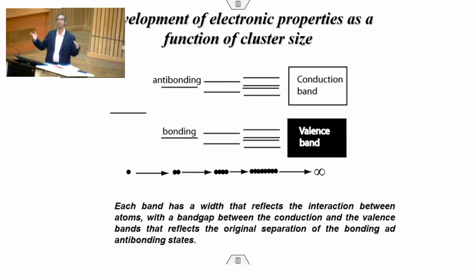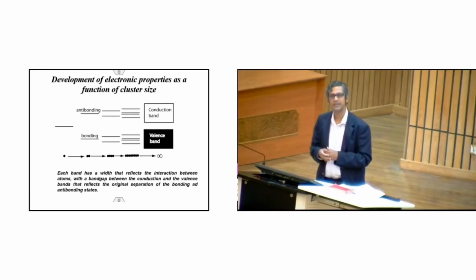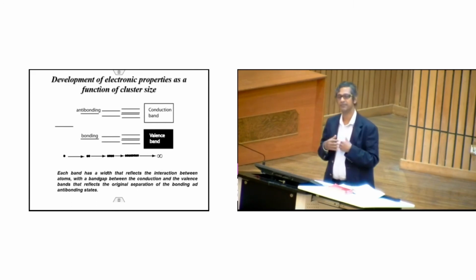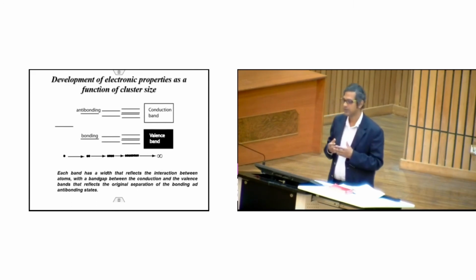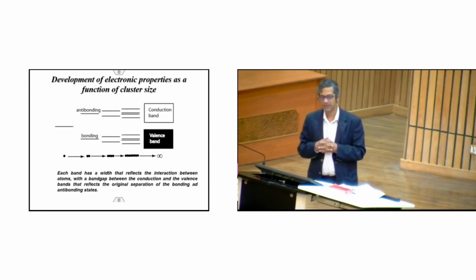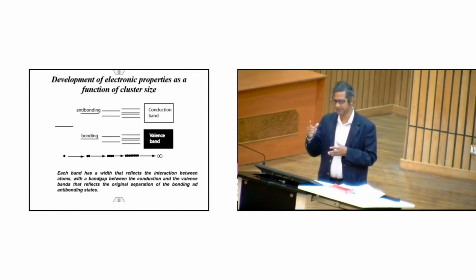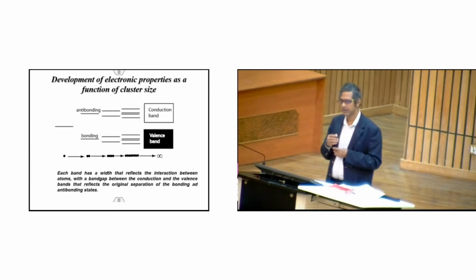They are moving from one place to another place. If you put a gas here, and if you allow it, it will diffuse from this place to some other corner of this room. Same thing in a metal, electrons are freely moving. So therefore, there is no band gap. But in a semiconductor or an insulator, there is a definite band gap. Electrons cannot simply move freely. So in a semiconductor, the band gap is small, so if you provide some energy, thermal energy, or maybe dope with some elements, then you can actually move the electrons from the valence band to the conduction band.